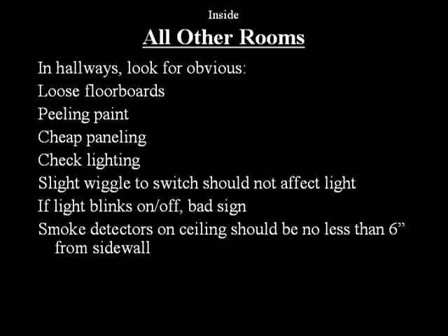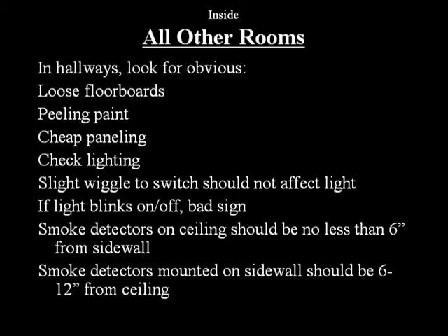Smoke detectors on the ceiling should be no less than 6 inches from a side wall. Smoke detectors mounted on a side wall should be 6 to 12 inches from the ceiling.